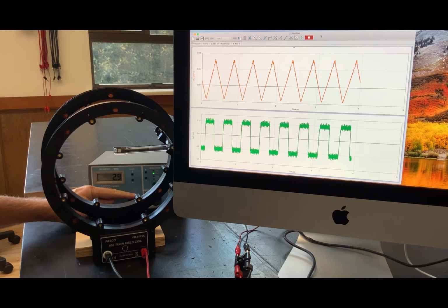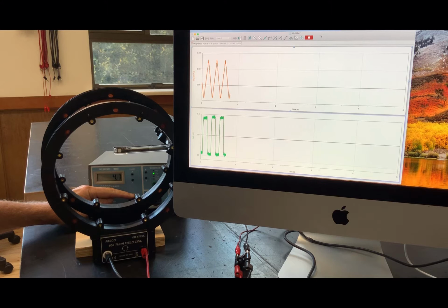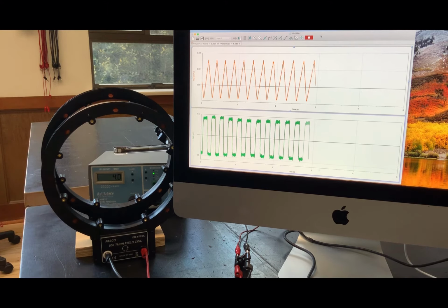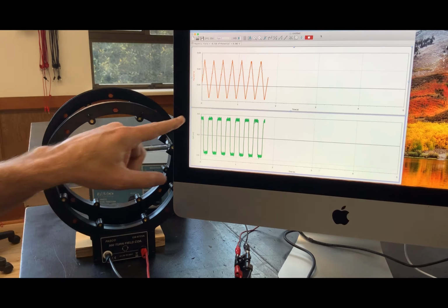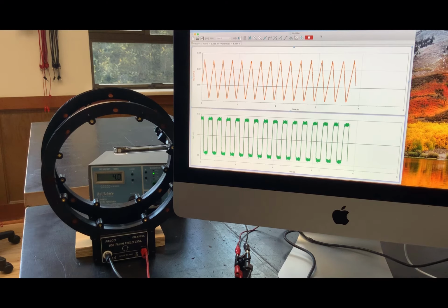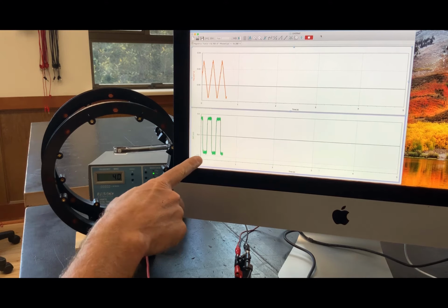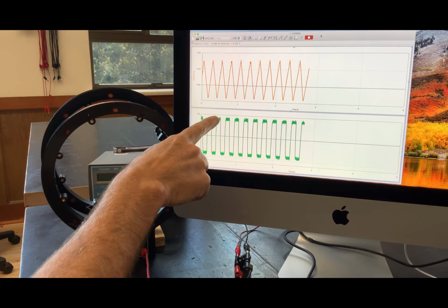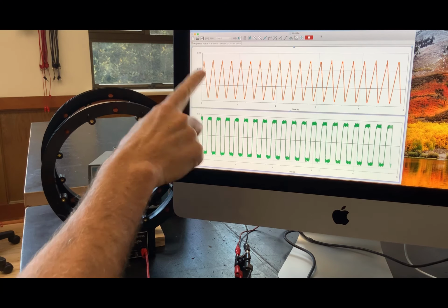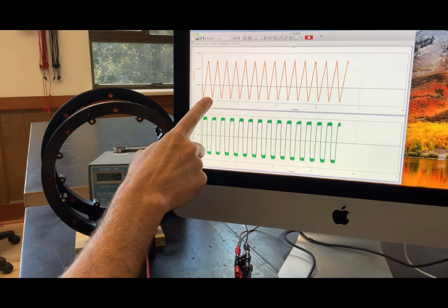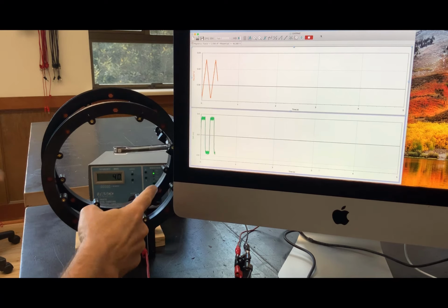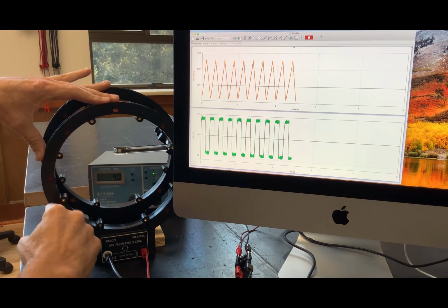And if we double this again, let's go up to 4 cycles per second. So now it's even shorter time. This is doubled again. And indeed we find the physical law is that the voltage here is actually the slope of this graph. Now what I didn't tell you is that in this graph I multiplied by the area of this loop.